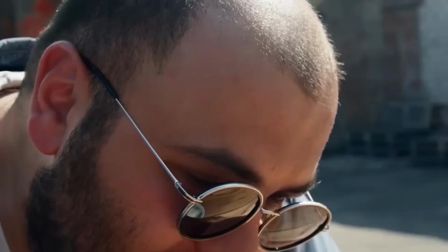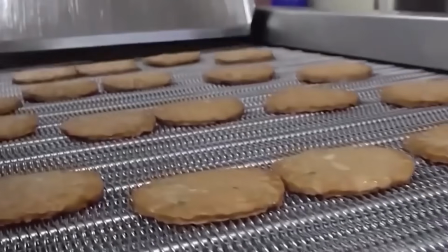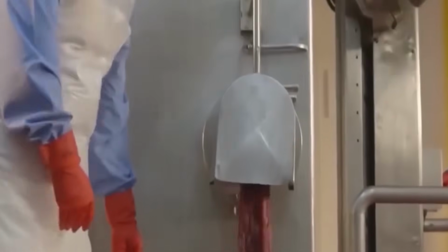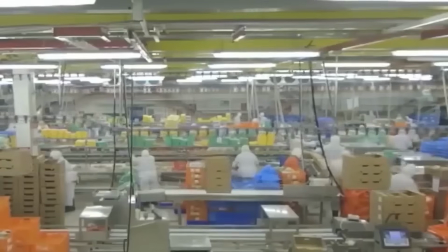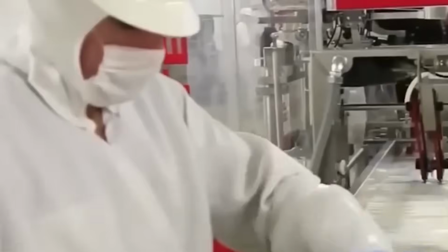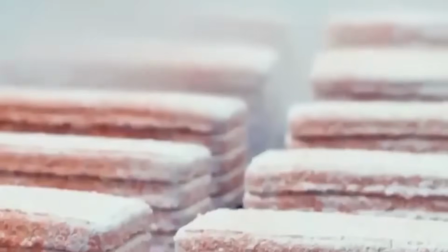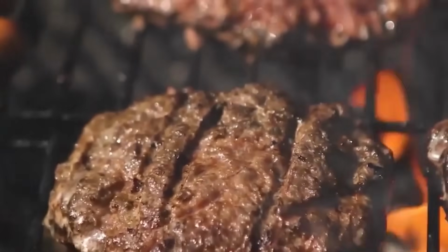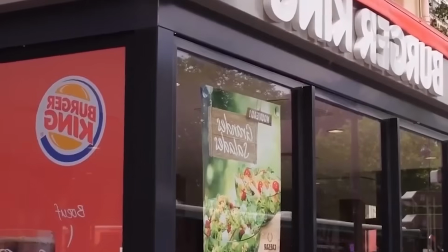Restaurant operations follow a grill-to-order or batch preparation method depending on volume. Cooking is done using a proprietary gas-fired broiler system equipped with a continuous stainless steel chain conveyor that transports raw patties through a tunnel with overhead and under-fired direct flame burners. Each patty is manually placed onto the moving broiler belt, which advances at a fixed speed preset according to patty thickness and desired internal temperature.